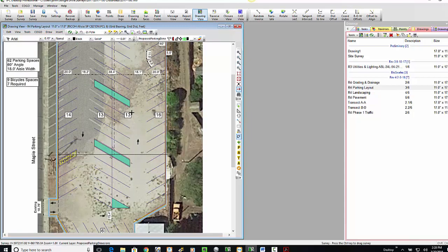And you can probably imagine we're already talking about how we probably will pave all of this to begin with and then come back later and dig these interior islands out. It's too hard to pave around these. Gary and I talked about it, and we've both done these projects in the past where you put in all the rock, you put in all the pavement. I'll come back later on and stake these out with some paint. He'll take his cutter in and cut these out, dig through the rock, try to salvage that, and then dig down and create the bedding area for the plants.